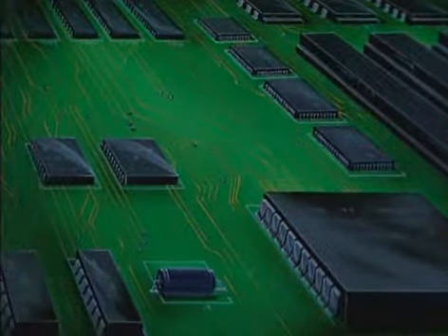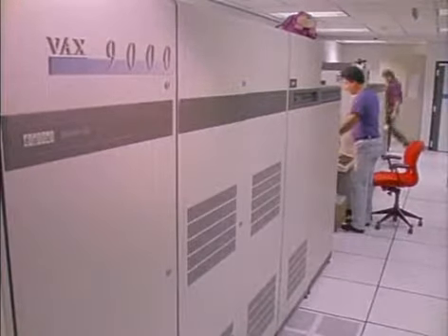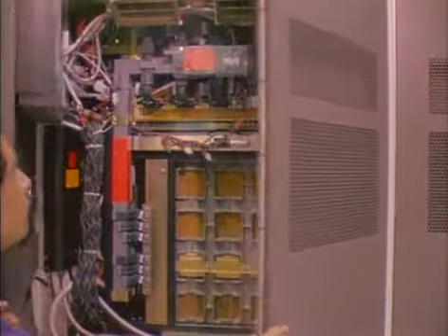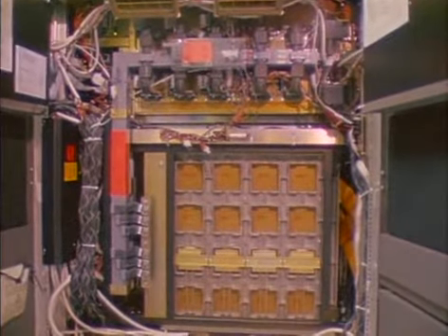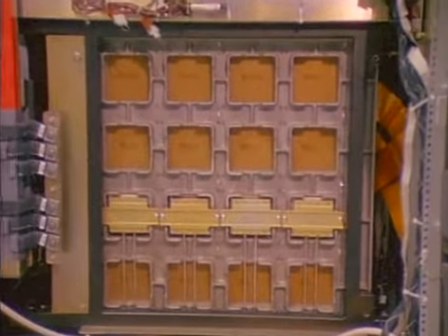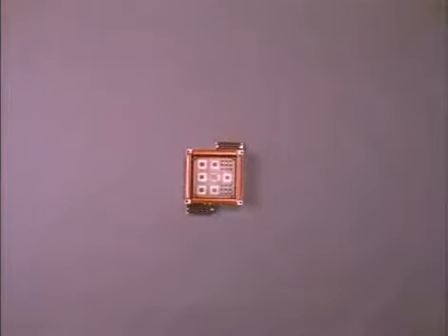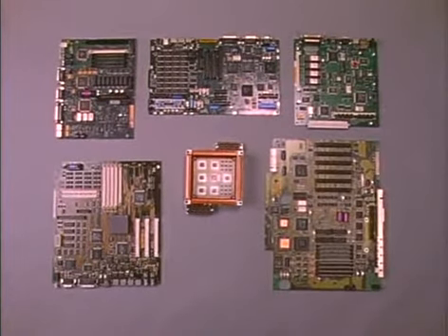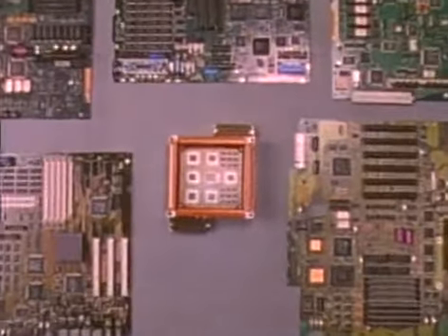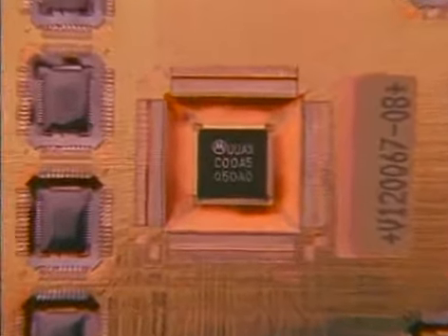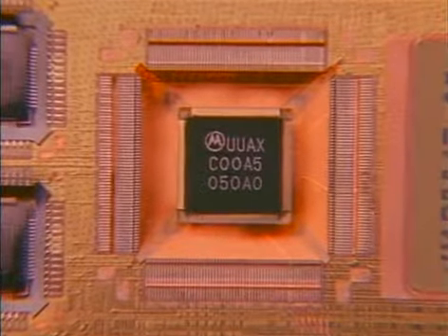To overcome these problems, this high-end computer uses multi-chip technology to enhance performance. From the back, we see one example of a planar module with the outline of 16 multi-chip units, or MCUs, working together. Each one of these units contains the logic, formerly mounted on several much larger printed circuit boards. High-powered chips are packed into these small units, along with the central clock chip that synchronizes with all the MCUs in the system. The board